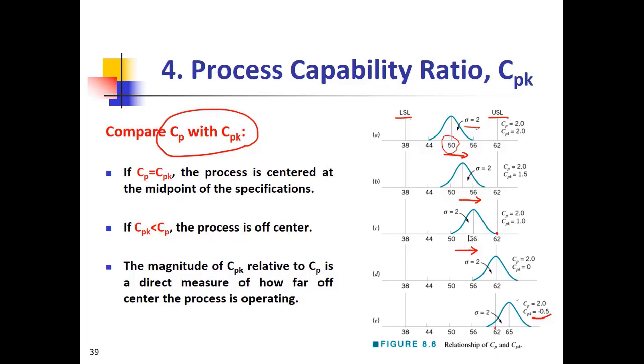In all the cases, they are very well distributed within 2 standard deviations of the mean, which is good. The 2-3 standard deviations from the mean is good, but CPK also gives us some information on how the data are distributed between LSL and USL. So most of the time, we need both these parameters together to reach a final conclusion on whether my data are very well distributed or not.